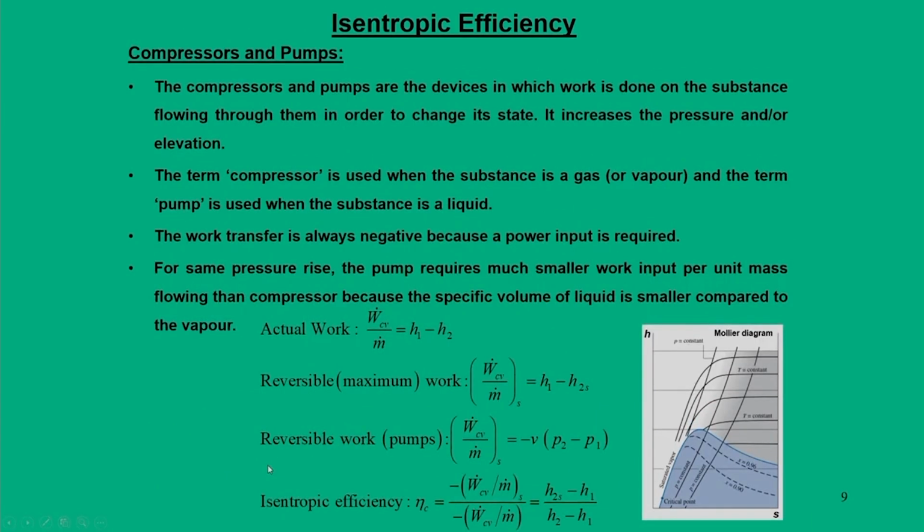Now, we will move to compressors and pumps. The word compressor is used for steady flow devices which take work as an input, that means work is done on the system, and by virtue of this the pressure of the fluid increases.